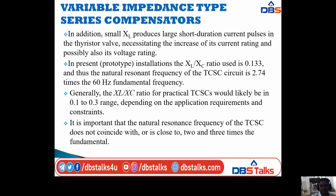In addition, a small XL produces large short duration current pulses in the thyristor valve, necessitating an increase of its current rating and possibly also its voltage rating.